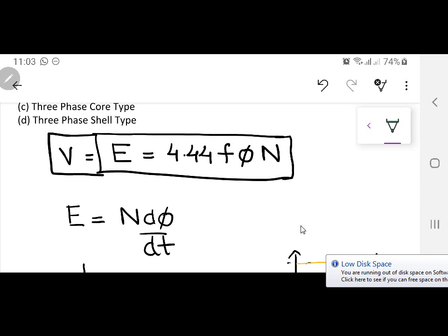In case of a machine, that is actually a motor. Or if it's a transformer, you are converting it back into electrical energy with a different step up or step down ratio. So this equation E is equal to 4.44 f phi N is actually the first building equation for any electromechanical device or any electromagnetic device.